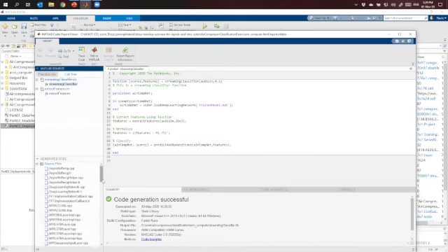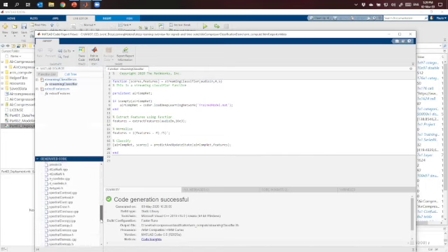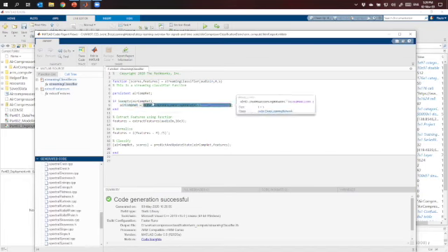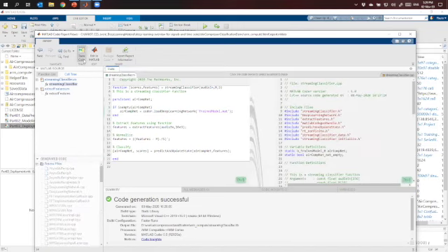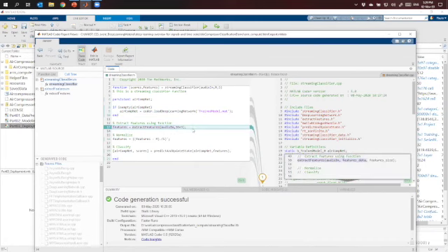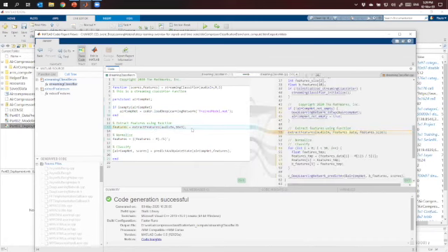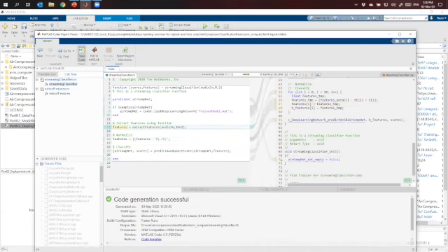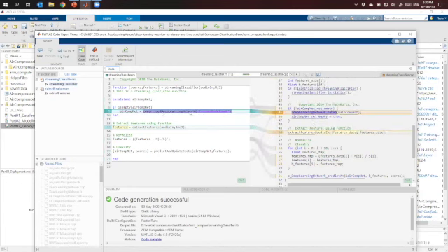And for example, what is the function? It's called a streaming classifier. So here, if you write, this is the trace code. That's a very good tool. What it shows is you have the line of code in Matlab, and you can see the line of code in C, and do the opposite. So you can trace every line of code in C to Matlab. See? This is very nice to see. I've never seen a tool doing this. So it's going to give you very good results.